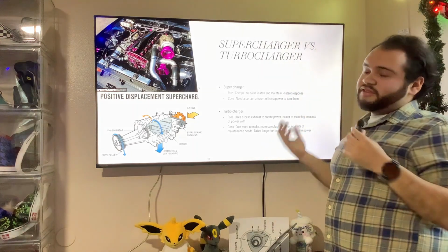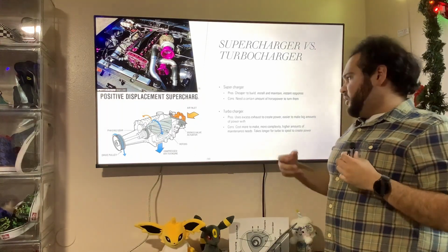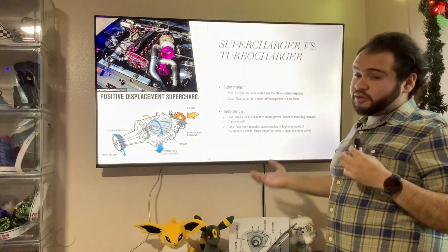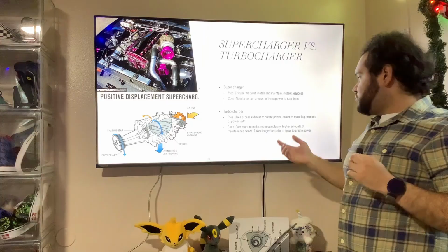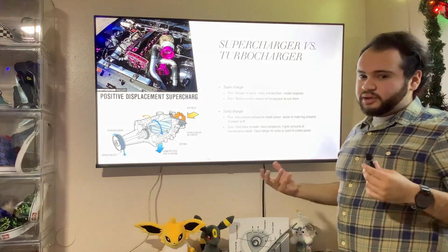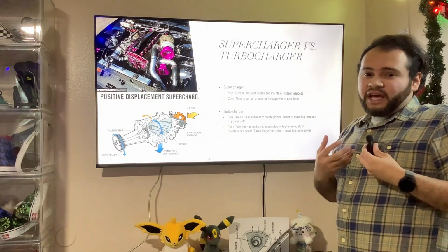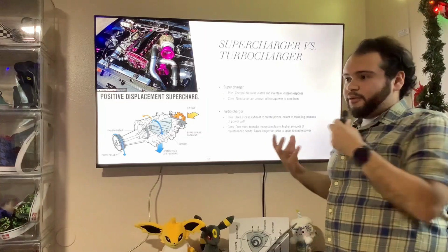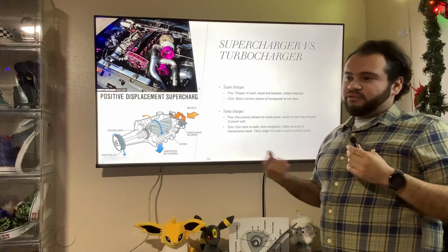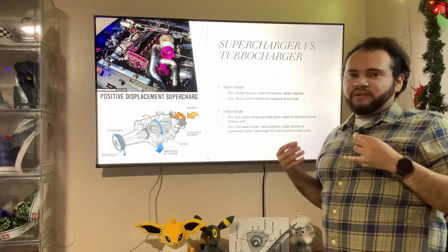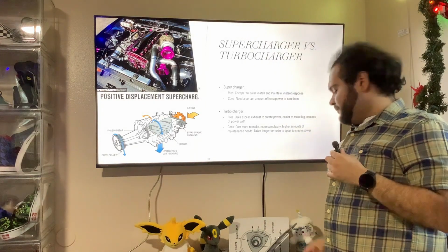Granted, the system's more complex. You've got to run more oil and coolant lines. You've got to wait for the turbo to spool up, which creates lag before the power comes. Also, they just cost more to build. But the pros are you're not putting more strain on the motor to create more power. You're creating more power more efficiently, which is why so many commuter cars and supercars use turbos, because it makes power more efficiently.